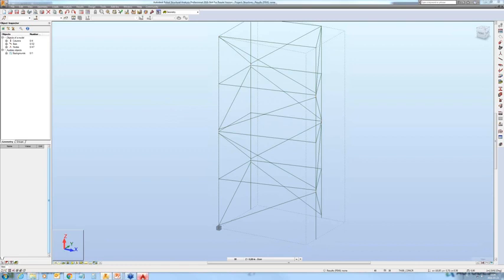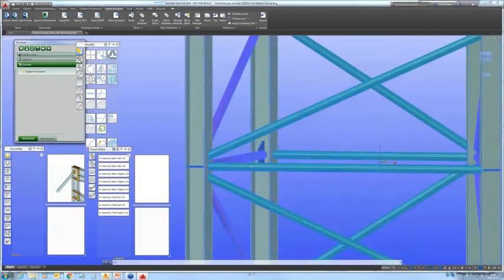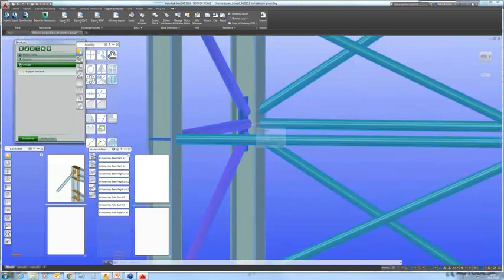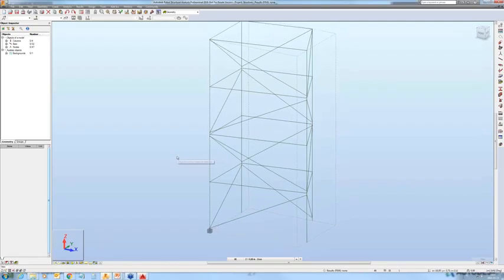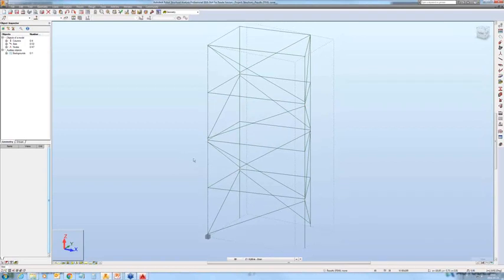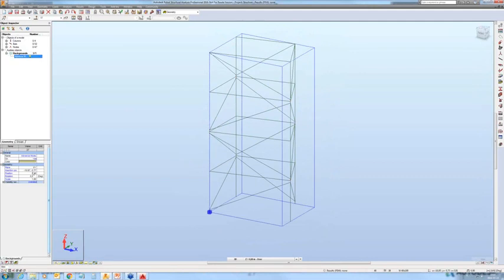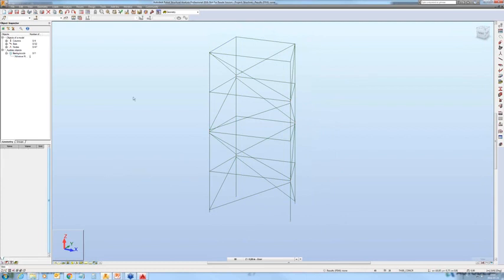So what I'm going to do, I'm going to show you for a moment in advanced steel the fact that this model has got a certain connections defined. And these connections include the gaps. So there is no common point for these elements. They are with gaps. But in robot, to, for example, use the steel connection module or to have a coherent results, we want to have all these elements to be actually snapped to a single position. So first, maybe I will just switch off the display of the background for a moment. I will also define the structural axis.